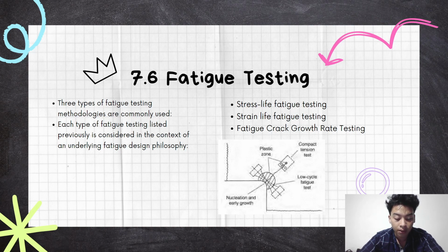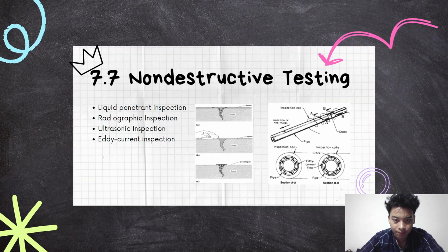Also, although S-N fatigue curves have some qualitative use for guiding material selection, the S-N approach is subject to limitations, primarily by the failure to adequately distinguish between fatigue crack initiation life and fatigue crack propagation life.